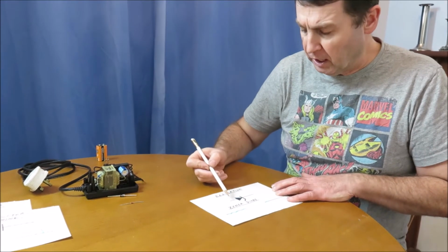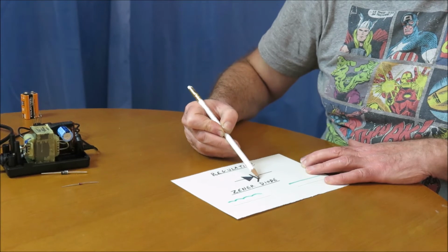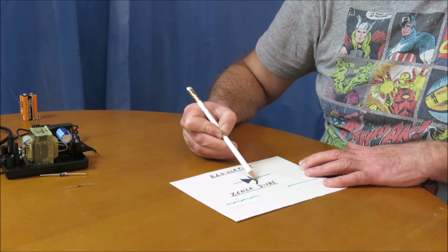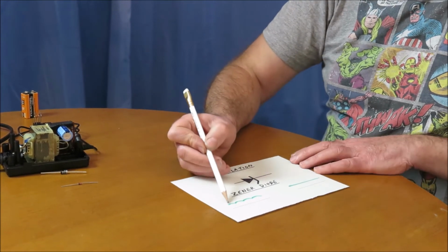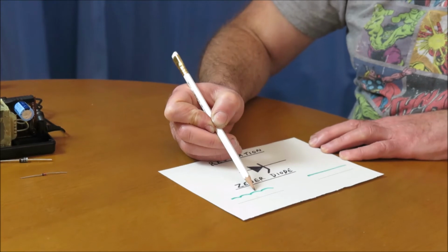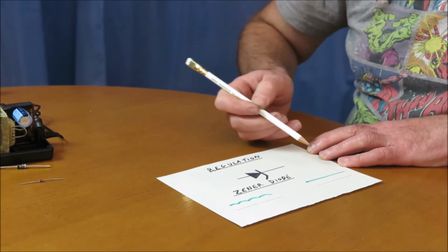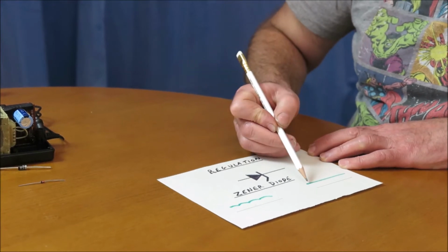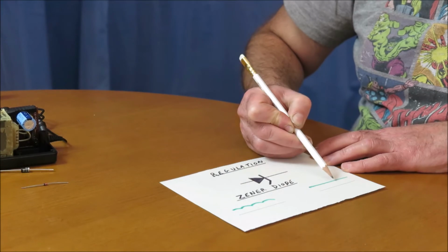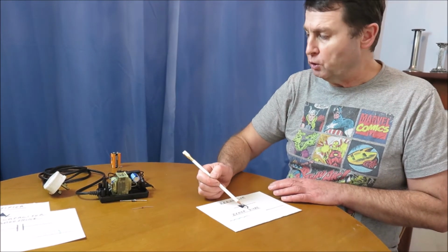And the symbol for a Zener Diode is like a normal diode, but with a little line going off the cathode side. That's the anode side, that's the cathode side, and with a little line going back. And here's the ripple voltage coming off the smoothing capacitor. But after the Zener Diode, this is called regulation. And after the regulation, we get the solid line out that we wanted with the battery. So that is what the components within the power supply do.